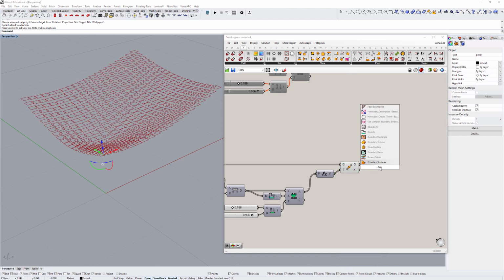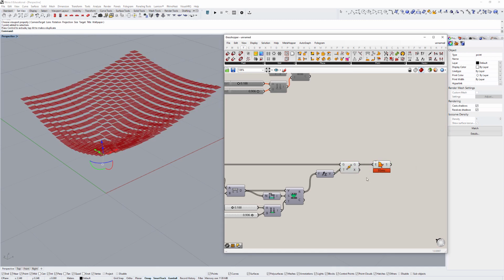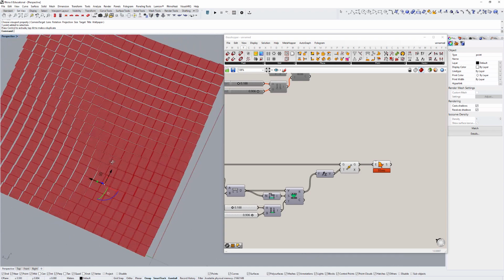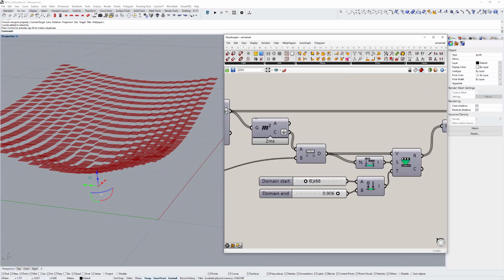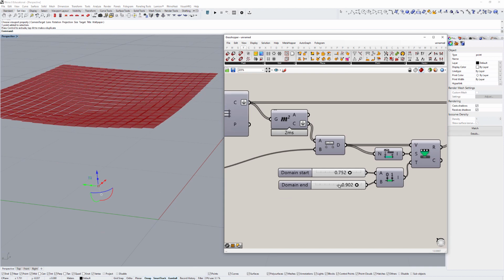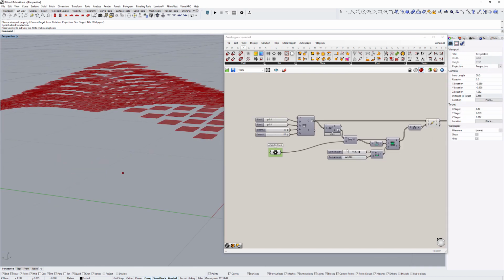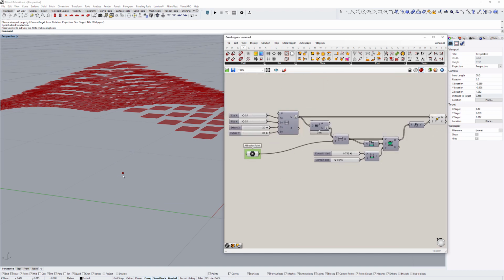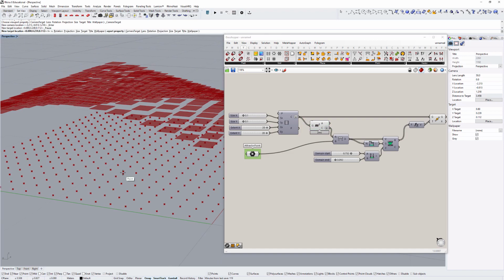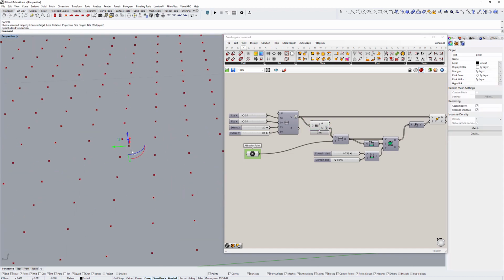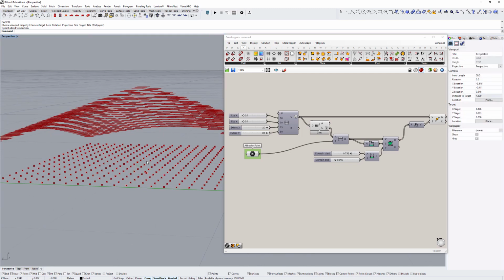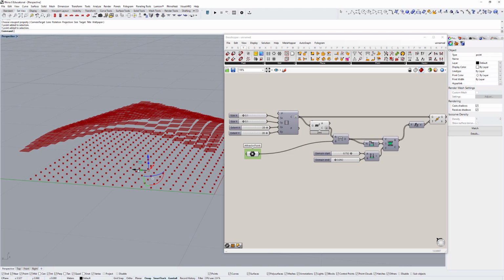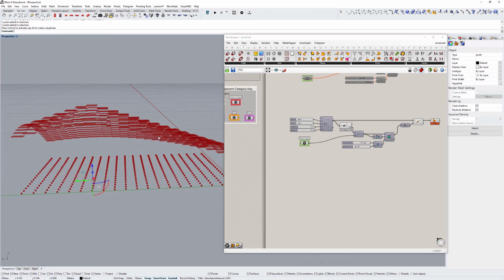Again, let's boundary surface that so we can preview it nicer. If you want the inverse, you just make your minimum number higher and your maximum number lower. So that's saying the line that is the shortest between the 2 points should actually push or move that surface furthest away. So you can see that if I turn on these points, we have those two being really close, and now we've set up an inverse relationship where that actually pushes our faces further away.